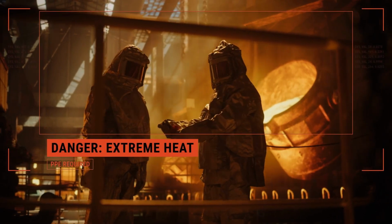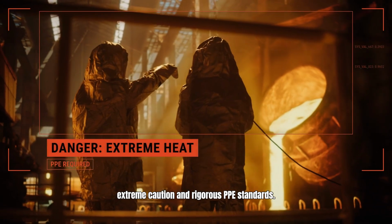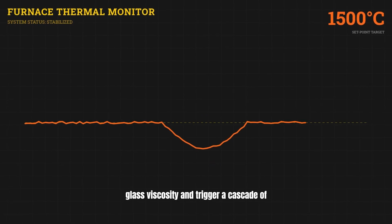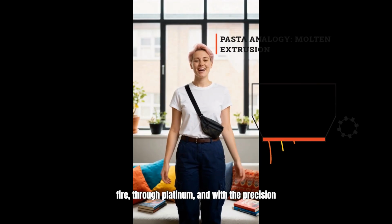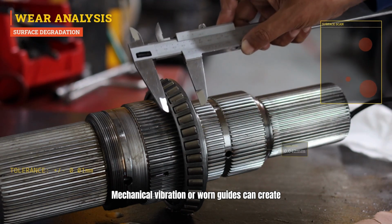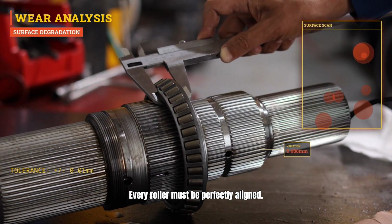Safety is paramount. Handling molten glass and high-speed machinery requires extreme caution and rigorous PPE standards. We investigate the furnace. Even a small temperature fluctuation can change glass viscosity and trigger a cascade of breaks. Think of it like making noodles, but from fire through platinum and with the precision of aerospace engineering. Mechanical vibration or worn guides can create fuzz and surface damage. Every roller must be perfectly aligned.